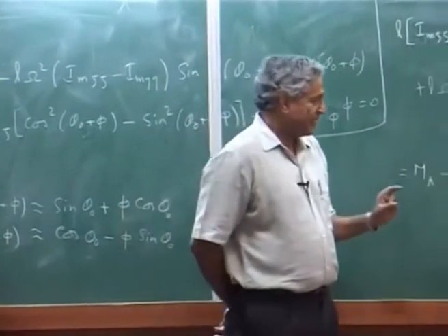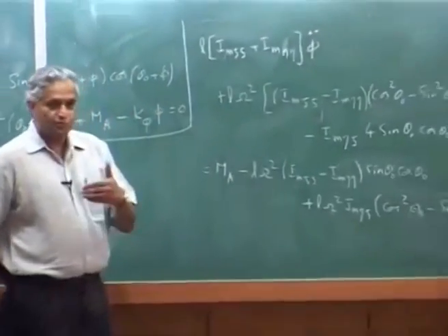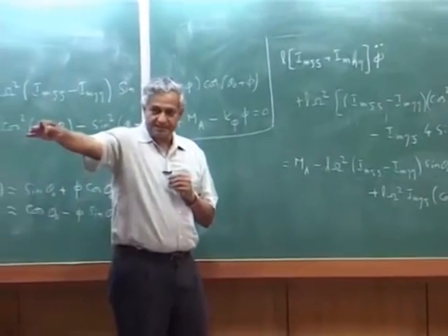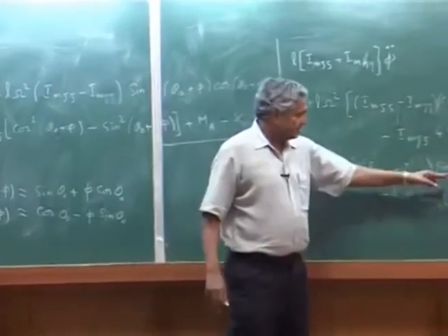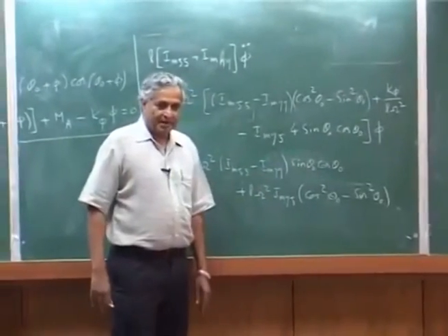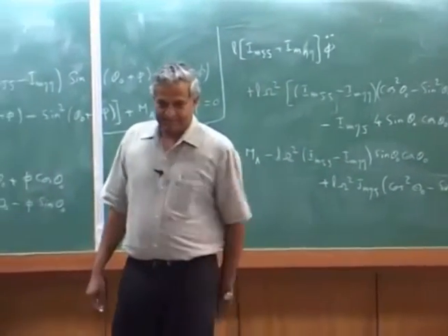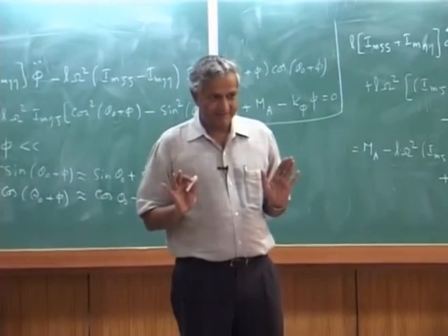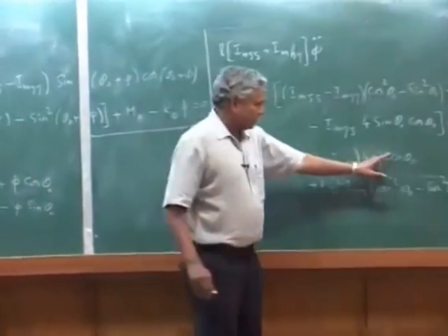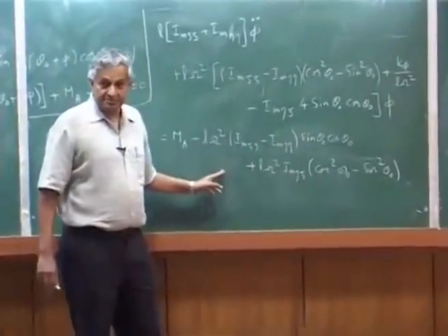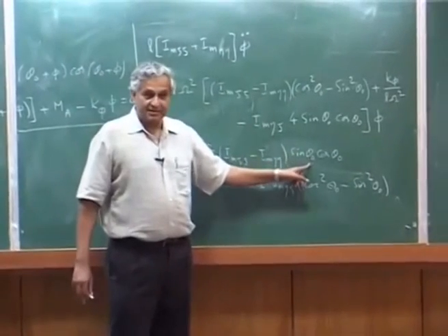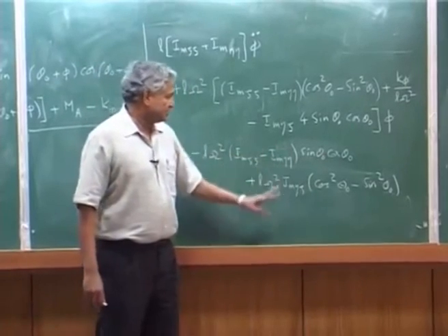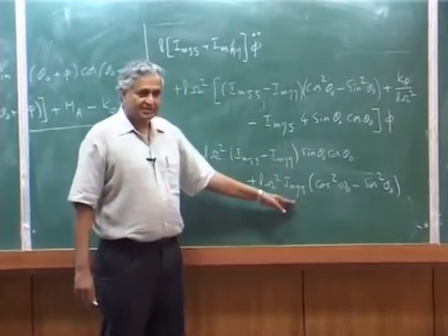So the idea is, this kind of tells you, even if you do not have any dynamics, you keep the blade at a pitch angle theta naught, and you rotate the blade. No aerodynamics, in vacuum. This is a constant term, which is a function of theta naught. If theta naught is 0, this term is 0, only this will be there.